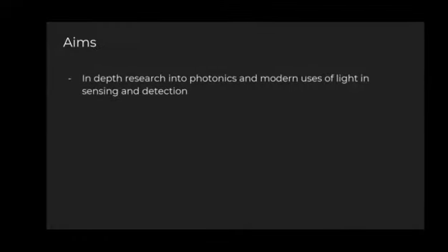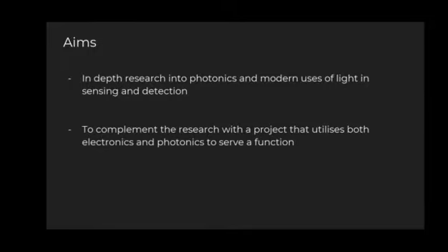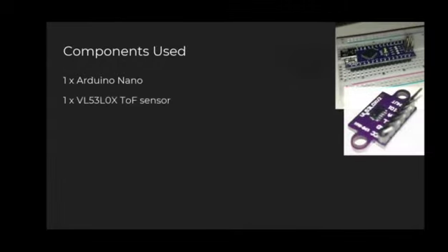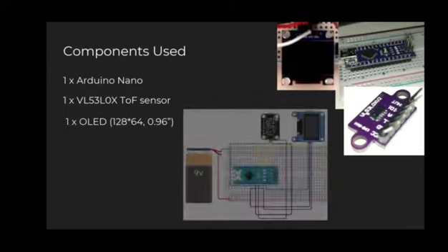This video will explore photonics, delving into the magnificent physics behind the time-of-flight sensors that allow us to detect distance and speed of moving objects. We will strive to bridge the gap between the physics and engineering in this field by combining the explanations with an appropriate project which demonstrates the function of LiDAR time-of-flight sensors. The project will utilize the functionality of both VCSELs and SPAD photonic devices within an electronic setting to create a speed sensor by measuring changes in distance.